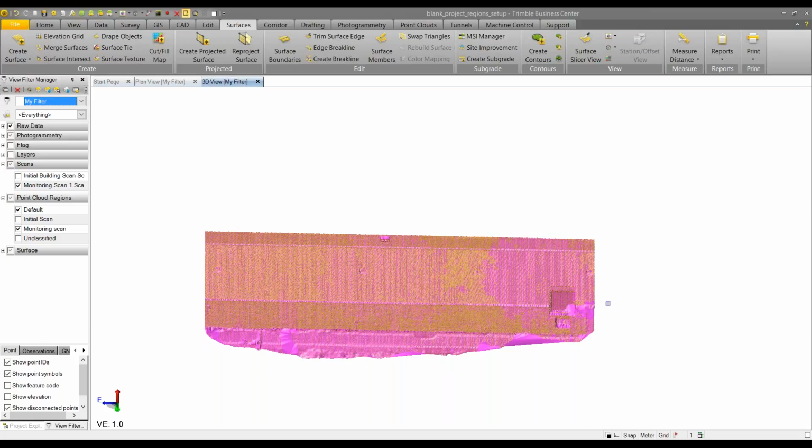So you'd be able to do what David is doing now, creating multiple projected surfaces and creating a cut fill map to compare one surface to the other, which will in turn then illustrate any cracking differences between the two scans, or cracks will also show in the triangulation of the projected surface object model, just like they would in any XY plane based surface.